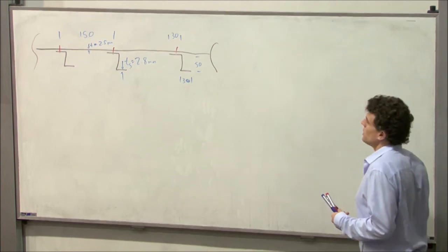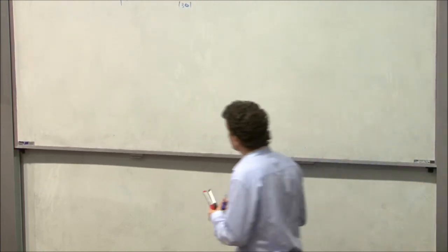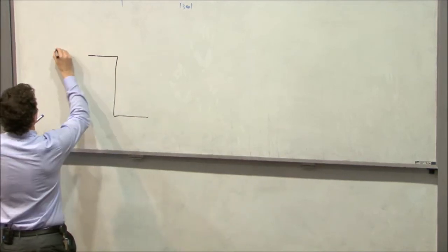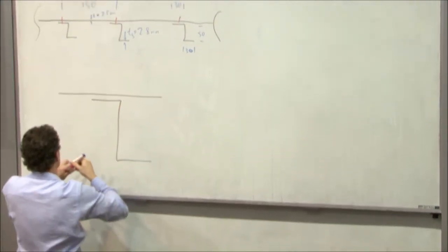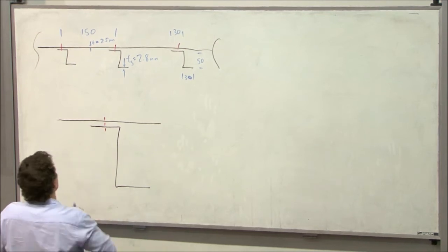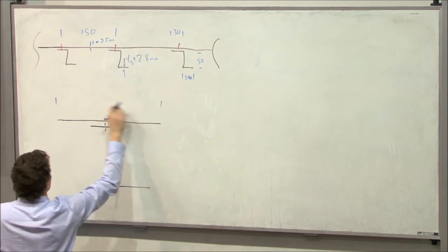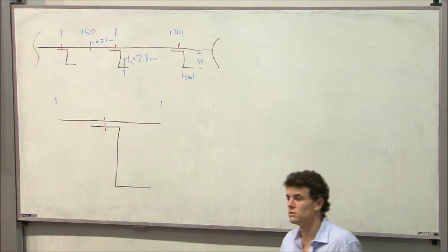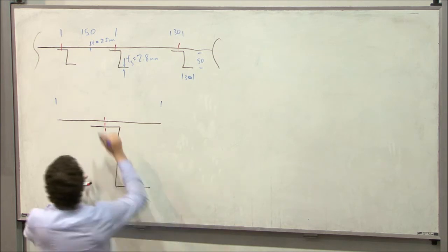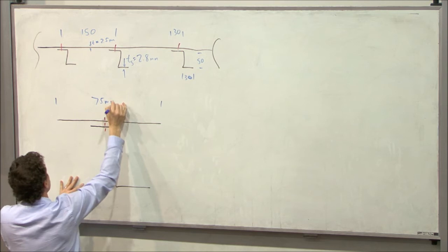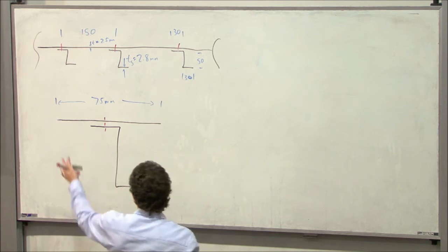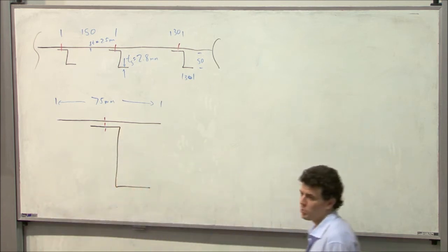Okay, so let's work out what the unit of stiffener that we're looking at is. I'll draw it a bit bigger. Here's my stiffener, here's my piece of skin, my fastener line. Now, how much skin do I need across here? 75 millimeters. Because of the skin buckling, I'm assuming that only half the skin is really active in helping this column resist buckling.